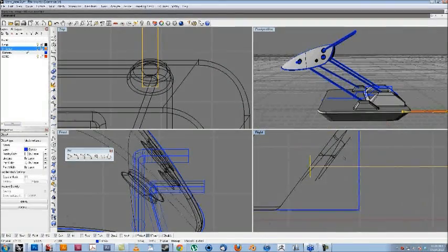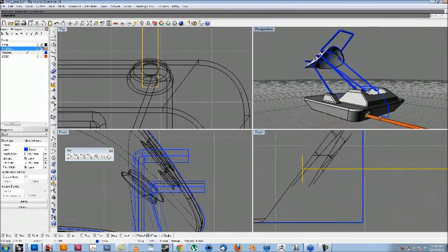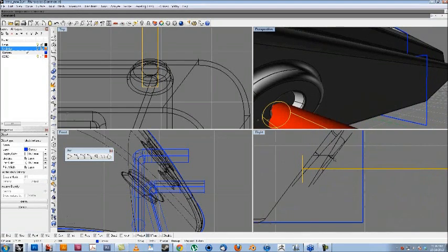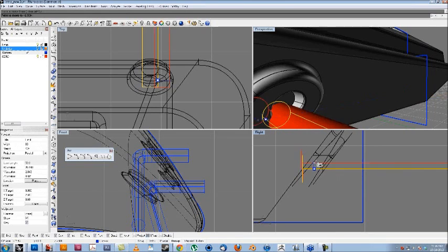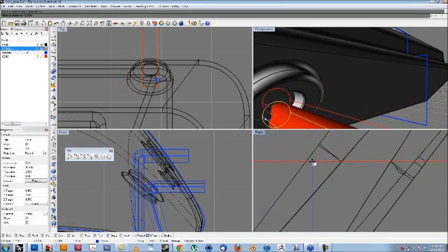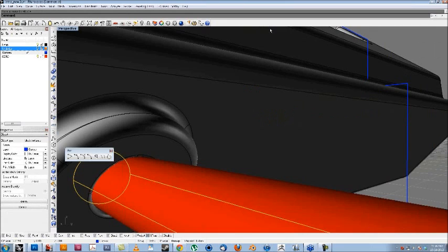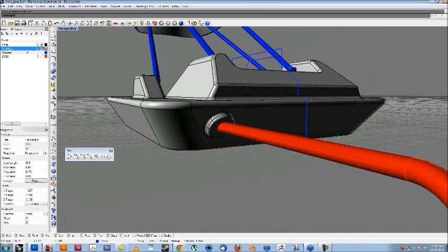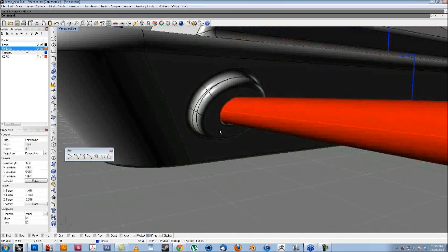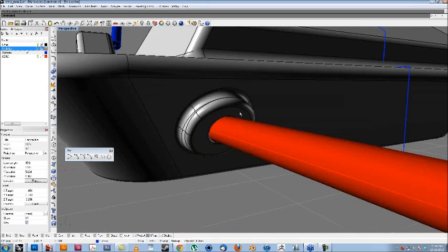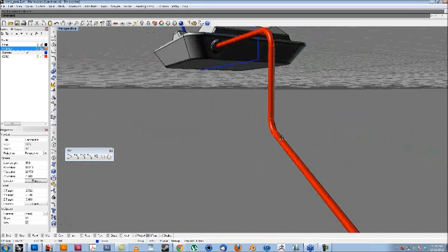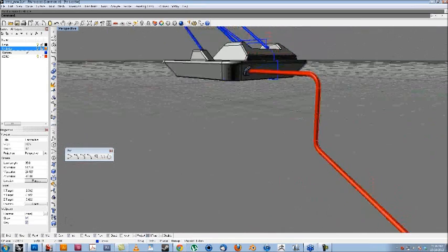Yeah, it looks good. Move it up. There are a lot of hotkeys within Rhino that make things move pretty quickly. I just used the M. If you just type M and hit enter, it'll automatically assume you meant move. And that's the power cord there.